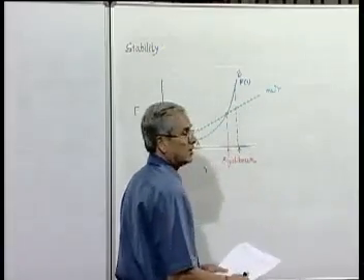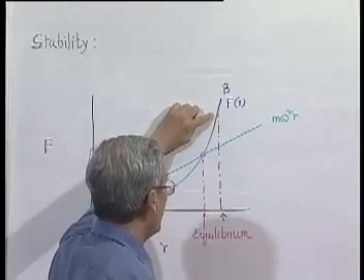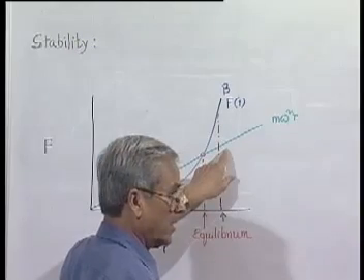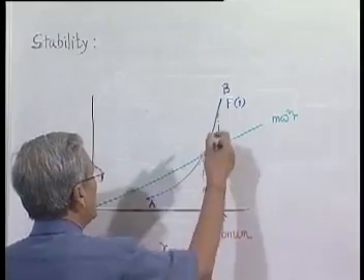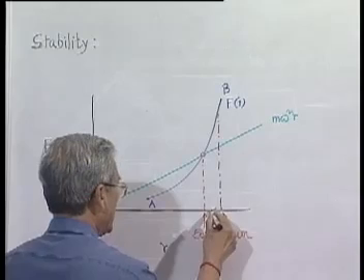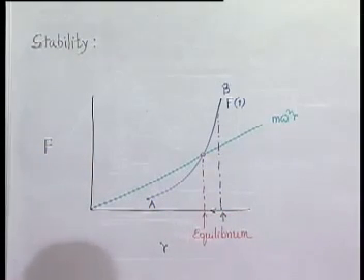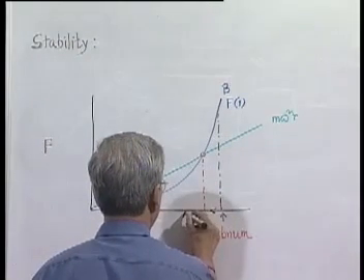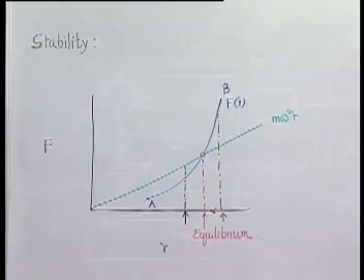Will it remain there? No. We can see that now the restoration, that is the control force, is more than the deflecting force, and the equilibrium is lost. Due to that, it will come back. Since the restoration is more, the radius r will reduce, and it will again try to come back to the original equilibrium position. Similarly, if we displace it to this location, we give a push to the ball so that it is pushed inward.